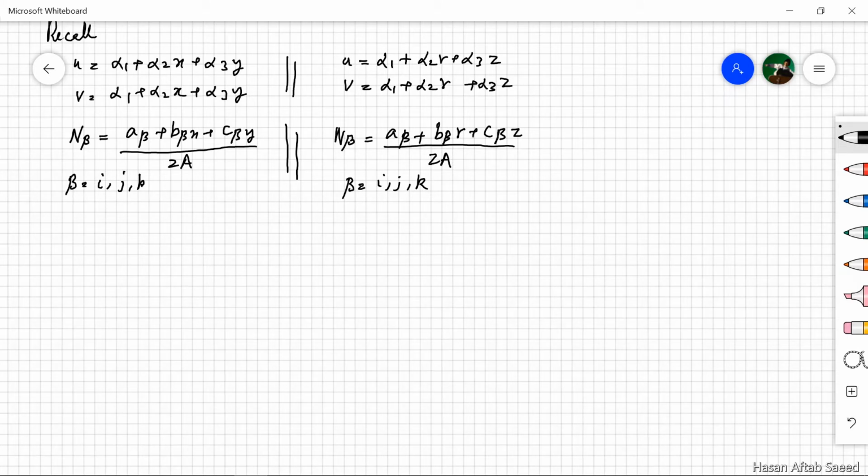Now the strains in the case of plane stress and plane strain problems, the in-plane strain components, were epsilon x, epsilon y and gamma xy. In this axisymmetric case, there is one more strain component, but before coming to that, the three strain components are quite parallel. In place of epsilon x, we have epsilon r, the radial direction; only the coordinate axis has changed.